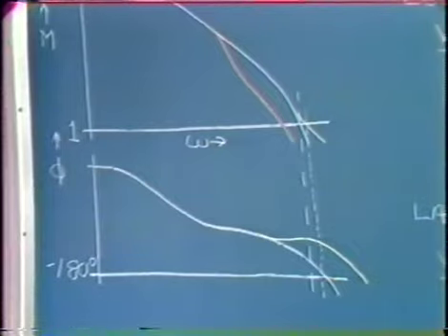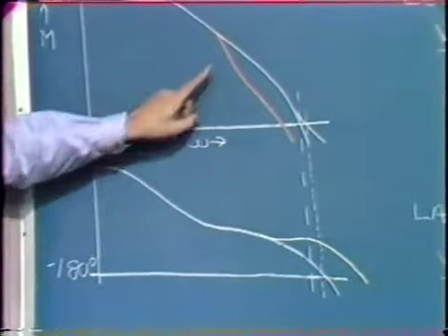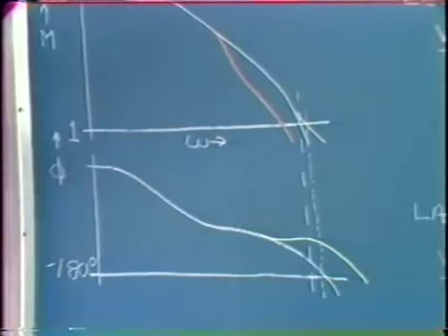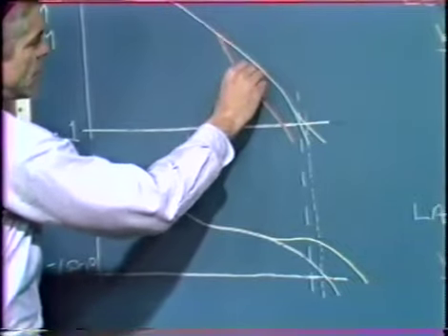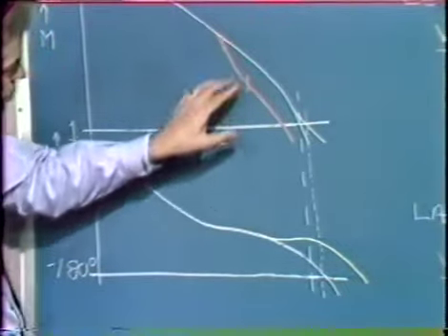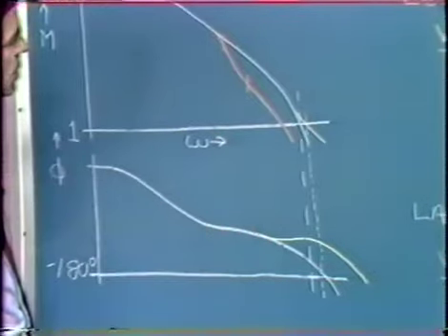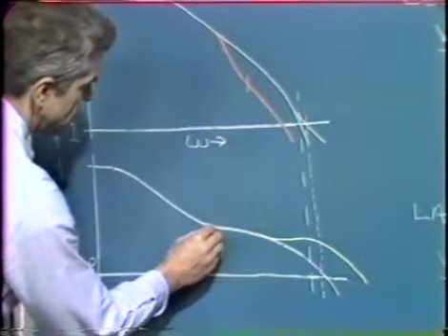What happens to the angle under those conditions? Well, here's the pole and here's the zero associated with our lag transfer function. And we recall from the plot of the angle characteristics of the lag function, and the lead function for that matter, that the most profound effect on the angle occurs over a frequency range between the two singularities, between the pole and the zero associated with the transfer function. So here in the case of a lag network put in possibly in this range, we'd anticipate that we'd put a negative lump in the phase characteristics. We'd do something like this.